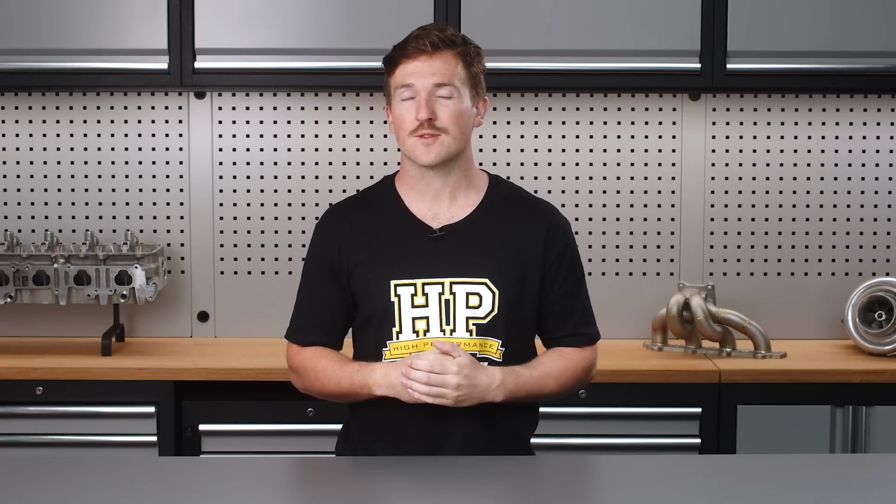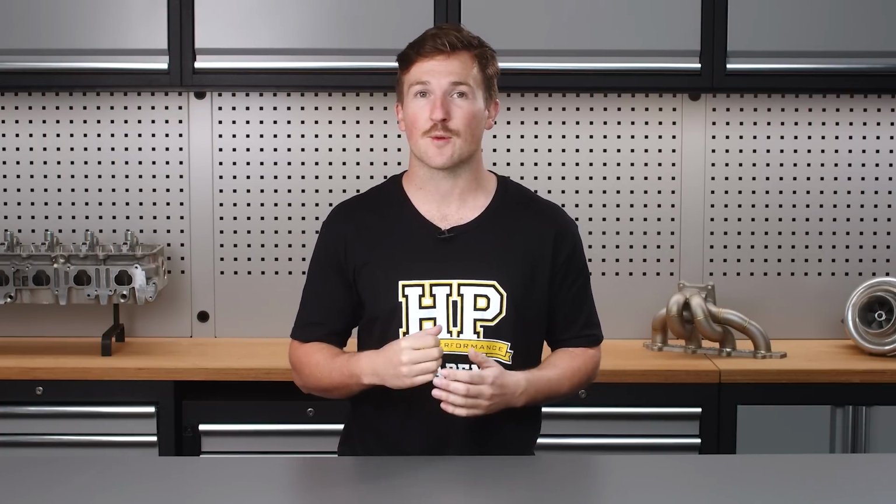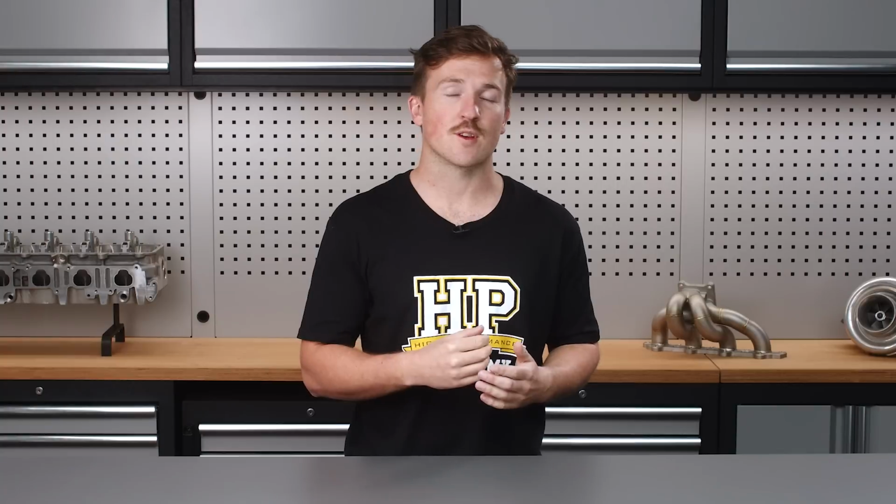We've covered a lot in this module, so let's recap the key points. Generative design is the process of our computer generating a design for us based on a range of inputs and specifications that we define. In Fusion 360, we need to set up the design space, including the geometry we want to keep and the areas we want to avoid, being the preserve and obstacle geometries. We can also use a model for the starting shape to have more control over the form of the resulting designs. Next, we set up the loads and constraints to outline the load case, much like the simulation process.